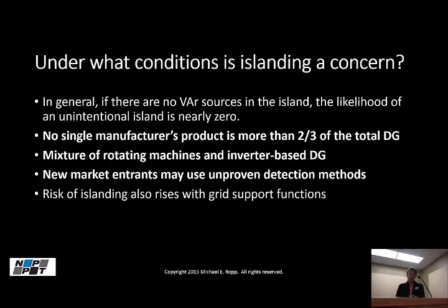So where do we start to get concerned? There are really two main cases that we worry about. I've subdivided one of them into two. That's why there's 3 bullets here. The first one is that if you have a mixture of different inverters in the island. It says different manufacturers here, but what it really is different product families, different types of inverters using different anti-islanding. The reason I throw that caveat in is because you can have inverters from the same manufacturer that might actually be made by different entities, so they may be using different anti-islanding.